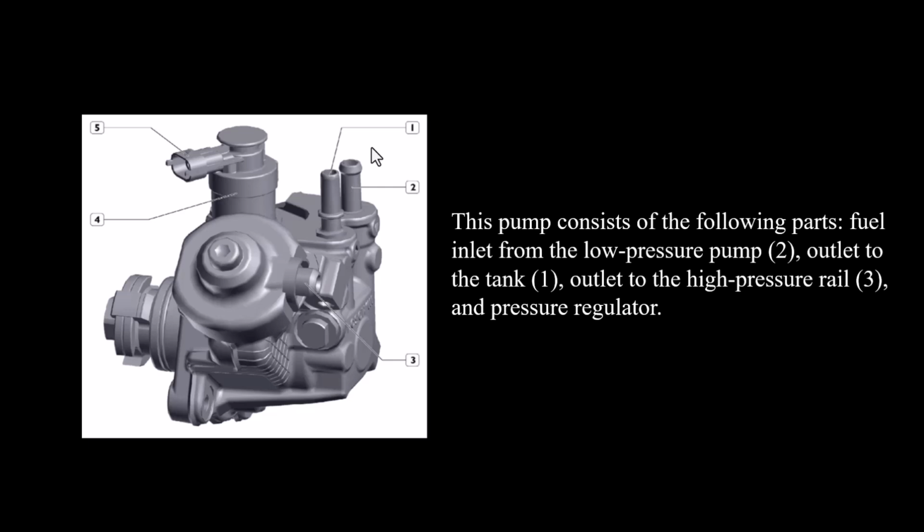Based on the type of pump used in the engine under study, as I said, a rotary or distributor, the fuel pump has been modeled in the GT Suite or GT Power software. Let's see the pump that I modeled in GT Power.